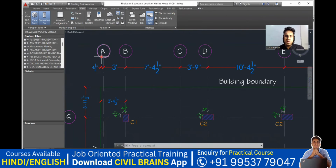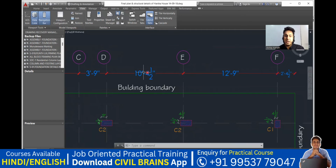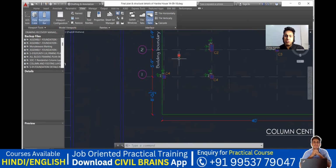Like the distance between grid line A and B will be 3 feet. B to C will be 7 feet 4.5 inch. C to D will be 3 feet 9 inch. D to E will be 10 feet 4.5 inch. E to F will be 12 feet 9 inches. In the same way, we'll start from here also.